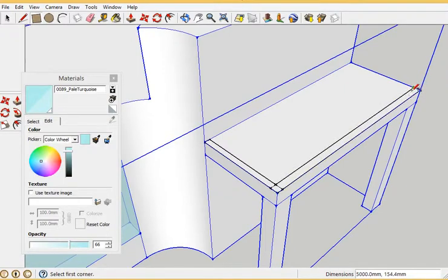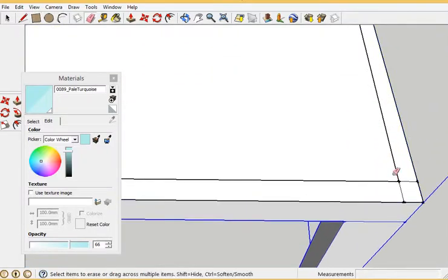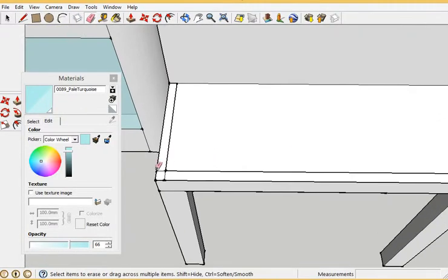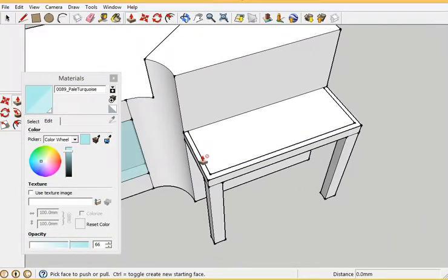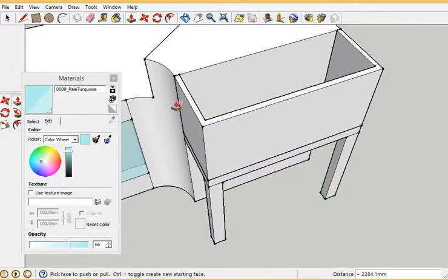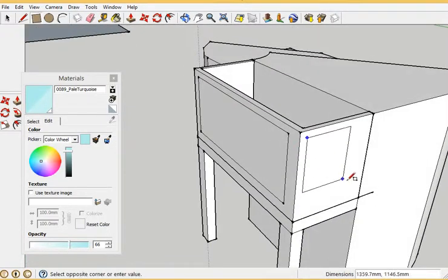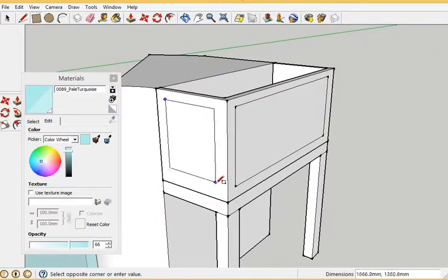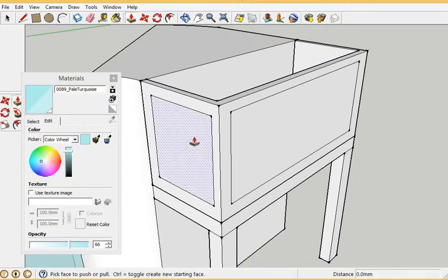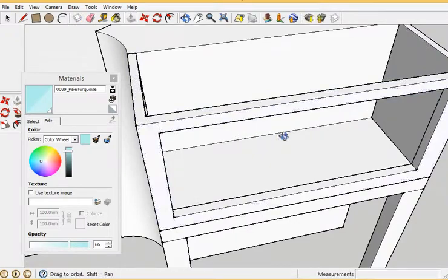The current layer is determined by this radio button here. So this is the current layer. So if I create anything new in this scene, it will show up in this layer. So for example, if I were to just draw a simple shape such as a rectangle, it's now in this current layer. So if I switch my current layer to layer 0, I can now hide my plants along with that new object that I drew into it. So when you draw things with a layered scene, you need to make sure that you're on the proper layer when you start drawing. I'm going to go ahead and select this object and delete it.